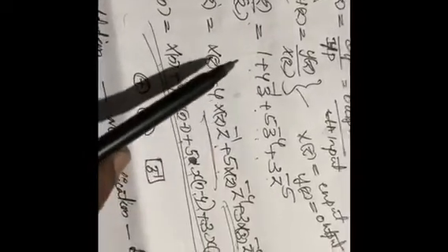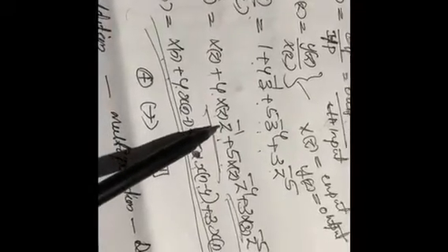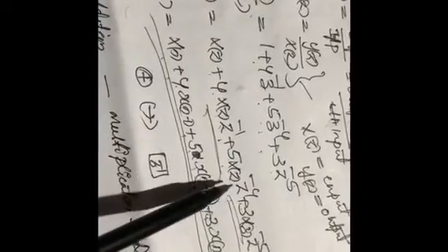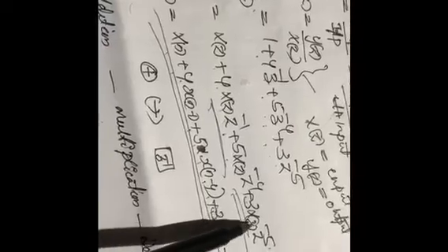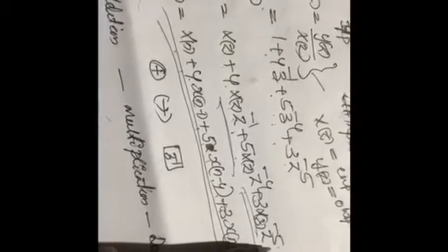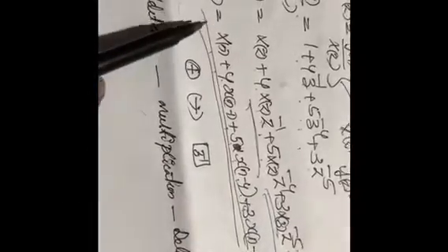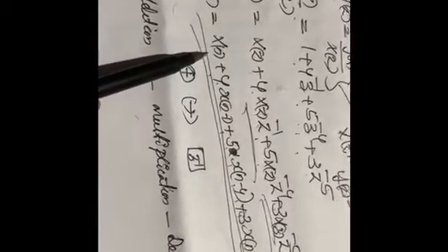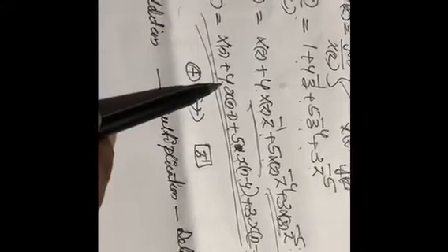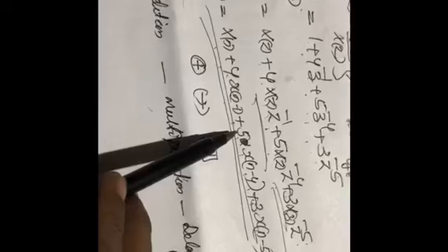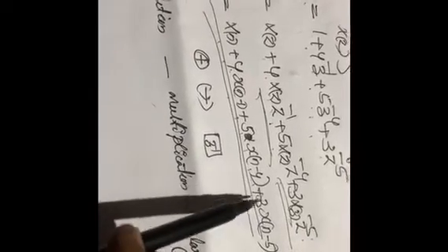Multiplying both sides by X(z), we got Y(z) is equal to X(z) + 4 X(z) z^-1 + 5 X(z) z^-4 + 3 X(z) z^-5. By taking the inverse z transform, we got y(n) is equal to x(n) + 4 x(n-1) + 5 x(n-4) + 3 x(n-5).